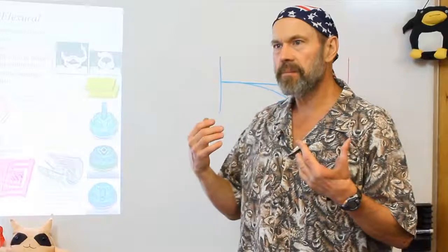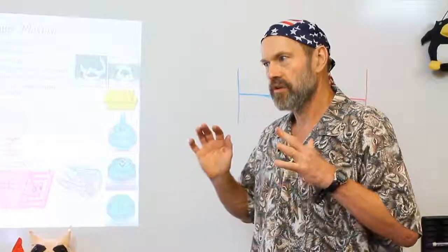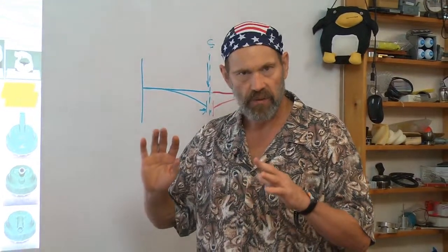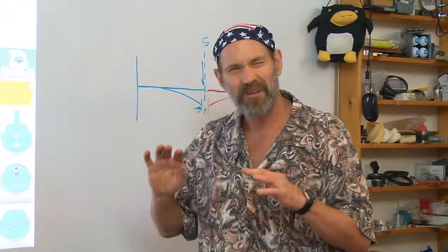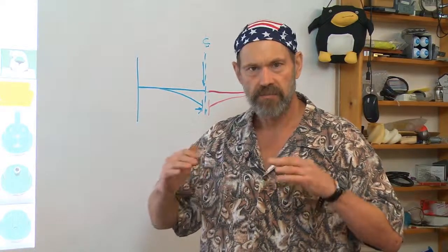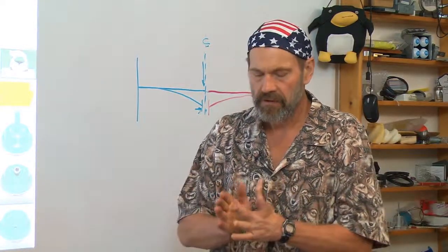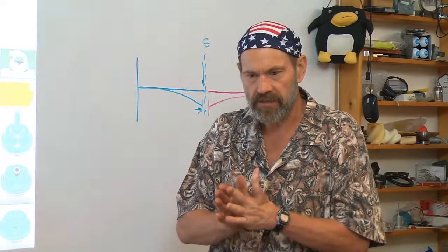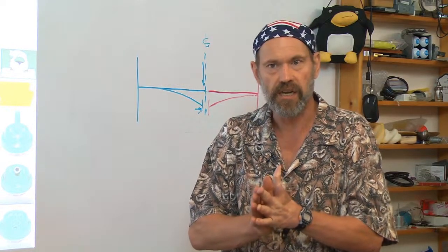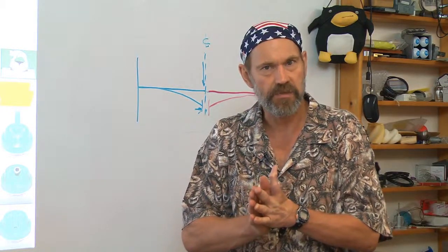This thinking about how bearings deform in the way you want them to move, and always being cognizant of what other little things are happening as things are moving, these parasitic motions, and being able to predict them, and being aware of them, and then determining if they're a problem for the functioning of your machine or not, is critical for the design of robust machinery.